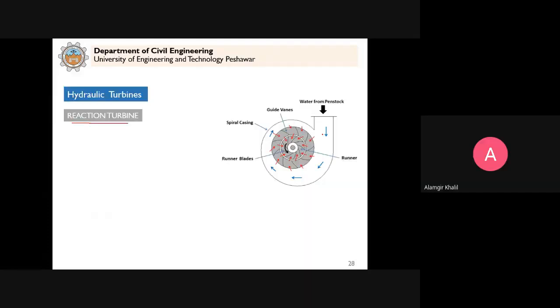Pump. So if you remember, in case of a diffuser pump, that was also called a turbine pump. That time I told you why it is called a turbine pump, because of its similarity with that of a turbine. So you see here, this reaction turbine, especially the Francis turbine, its working is very much similar to that of a pump, but in the opposite, reverse direction.